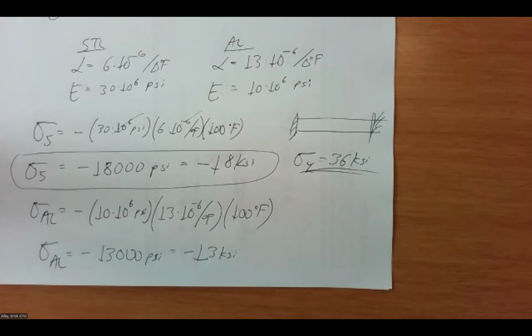And remember, we've got that dark, low observable non-skid on there that absorbs more radiant heat from the sun as well. So 100 degrees is very easy to achieve for a metallic structure change in temperature. And we can see what happens when we've got constraints around on a ship, lots of rigid constraints because the ship has a lot of structure around it.